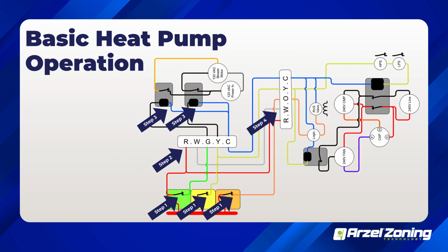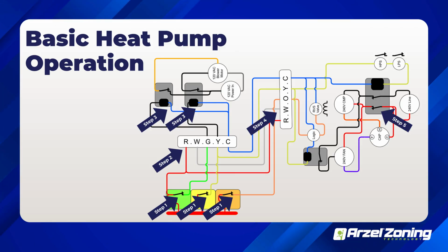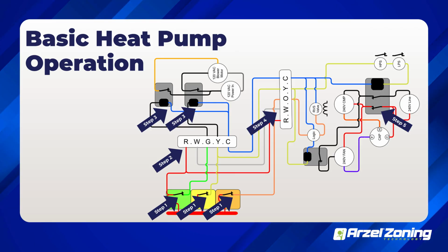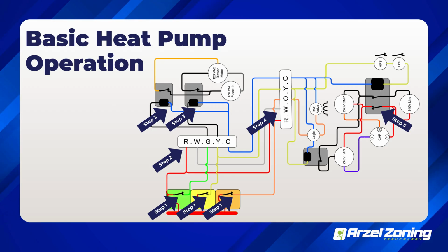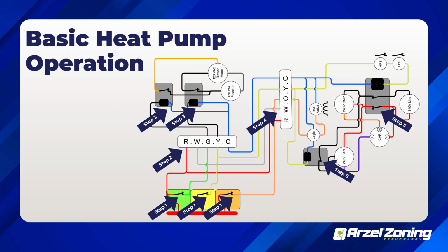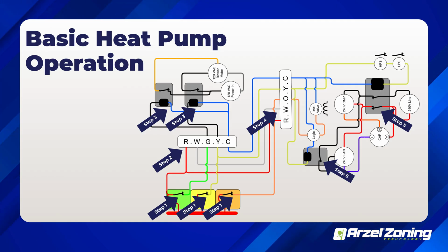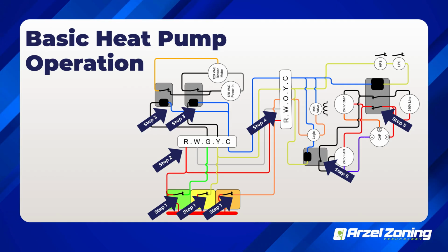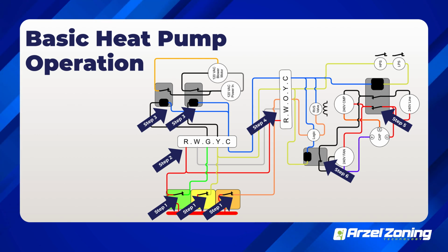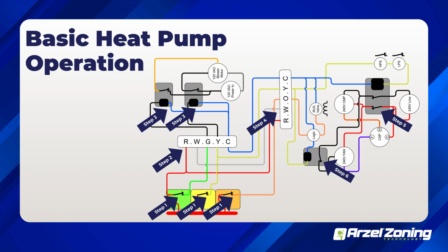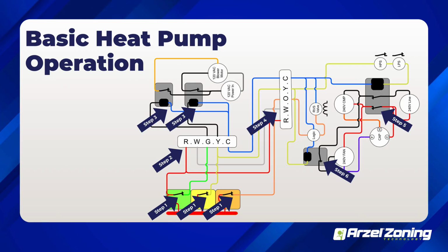And at the defrost board, we're going to determine, do we have our voltage out there? If we do, we need to see what's running. Did our contactor close? If it didn't, then we probably have a high pressure or a low pressure switch that's going to be open. There's really a lot to take a look at with the defrost board, but it's still all exactly the same. It is your relays, it is contacts, it is a low voltage controlling a high voltage source. And as we start testing for the voltage, we can start to knock things down to see where the problem's at.